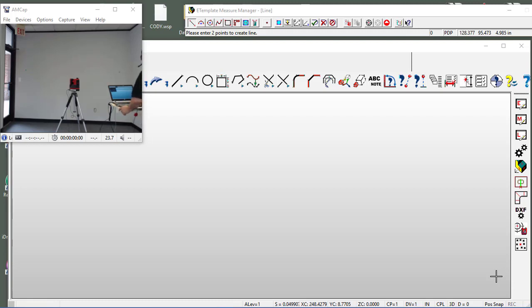Okay, this morning we're going to do a flatness analysis on this particular wall. This wall is roughly an 11 by 9 foot wall section. And the first thing we're going to do is move our construction plane to that wall surface. We're going to do that using this tool.